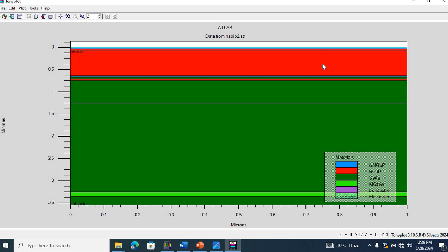Like this layer is n-type, so it's going to repel holes from this layer, preventing them from reaching the rear surface and recombining with carriers of the opposite type. So the back surface field is a critical component. I mean, every layer is critical. You need to care about the doping concentrations, you need to care about the thicknesses, and this is the significance of the back surface field.